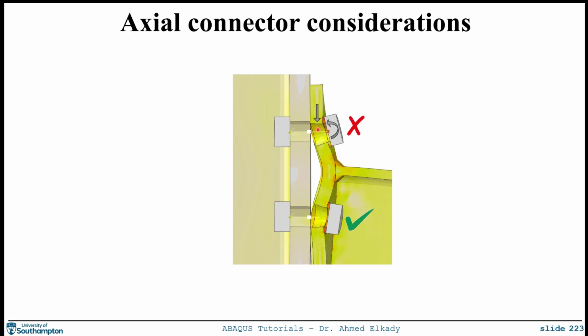In this case, therefore, it would be recommended to use the solid modeling approach for this specific bolt instead of the axial connector. Or you can still use the connector bolt model, but you will need to add an additional constraint to limit this relative shear or slippage movement between the plates. For your typical plus or minus 1 millimeter bolt hole tolerance, a 2 millimeter limit should be imposed for this relative vertical or shear motion, which you can do by defining an additional wire connector that will be acting in shear between the two bolt hole surfaces.